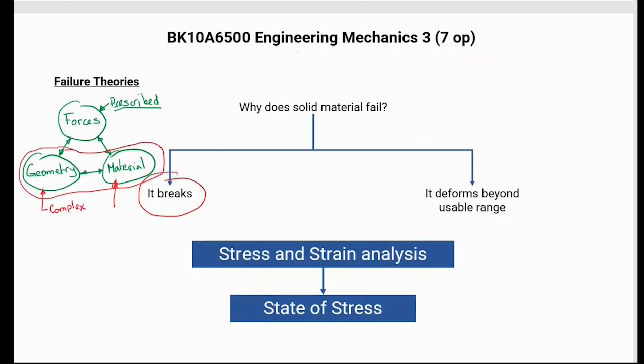For the case of material, there are even charts that you can use that tell you ranges or big ranges of application. It's going to say, okay, some kind of a diameter related to strengths, or something like that. Then depending on the type of operation, or velocity, you would just look at the values, and then it would say, okay, I recommend you to use, for example, well, this is North American nomenclature, so C45, something like that. For your application, we recommend this. Boom, and then you use it.